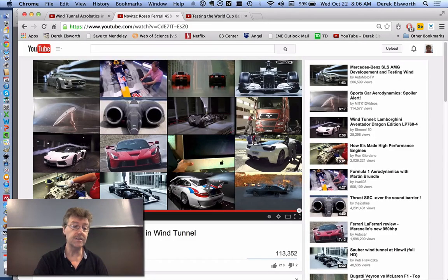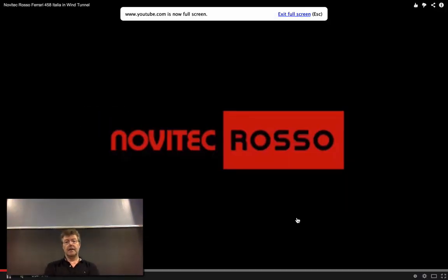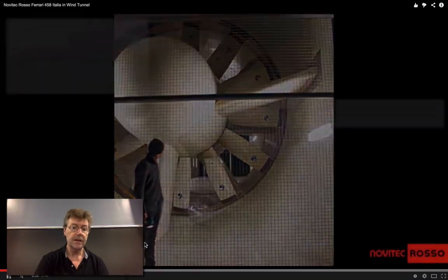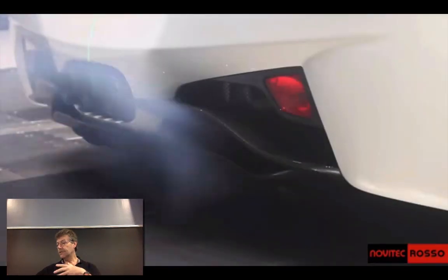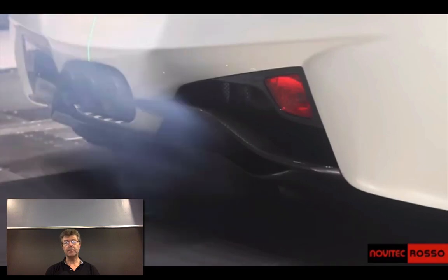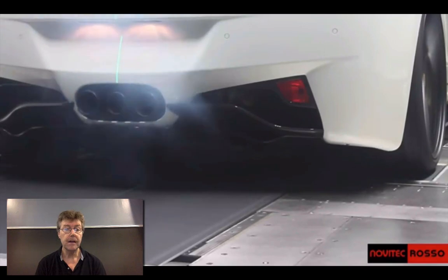And so it's really just the velocity squared term and the pressure term. So the same as a gust of air out of the jet engine hitting the truck that goes behind it. It's the same calculation. The Euler number is basically the number that comes out of the juggling of the pressure upstream, pressure downstream where it stagnates on the truck. You kill velocity, and the force on the truck is applied. The pressure on the truck is applied due to that destruction of momentum by killing velocity.